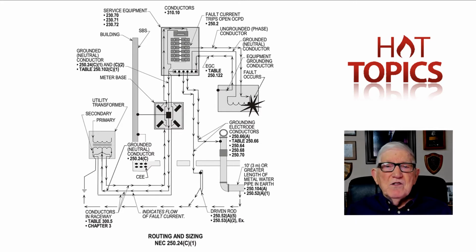You have to design by 220.61. For example, I might have, say, a 3-aught feeding this panel board with a 200 amp main. I may have a 4-aught conductor from table 310.16 supplying a 225 amp main.